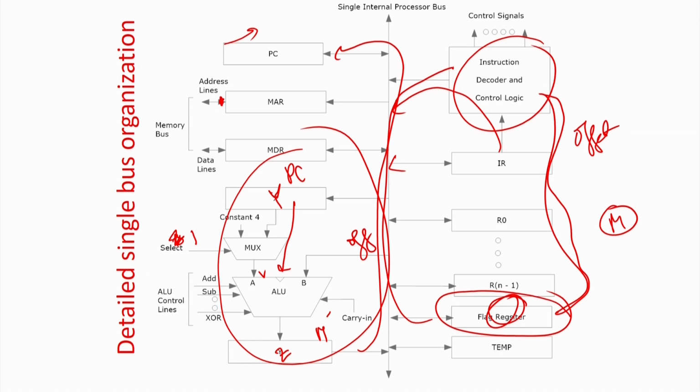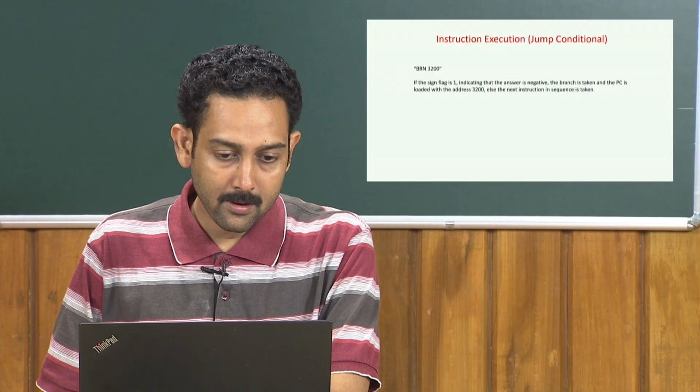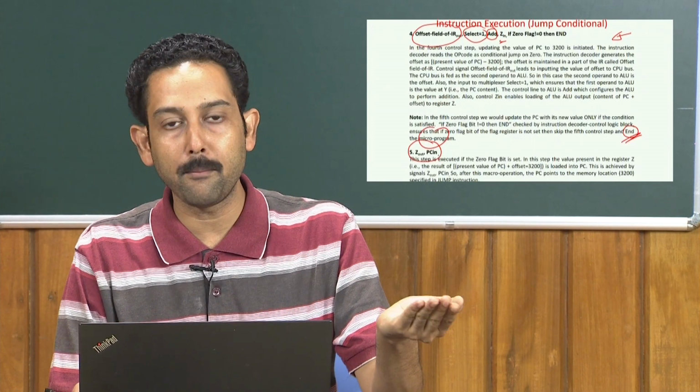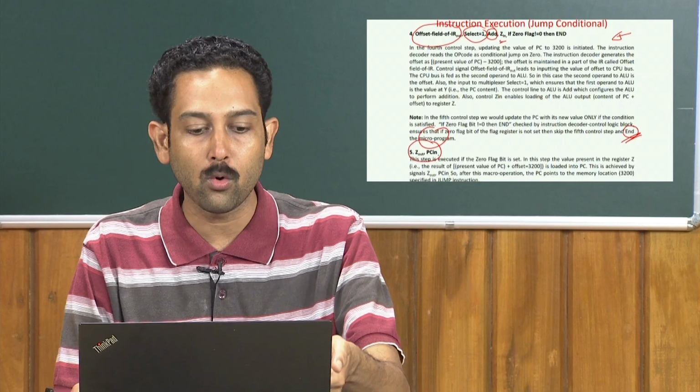Now, we will shortly see what call and return are. For the time being, assume that it just somehow resets so that nothing more gets executed and basically your micro program ends. So, there are 2 options. Either you end it, that is you return to the macro instruction and go to the next instruction, or you go to PC in.